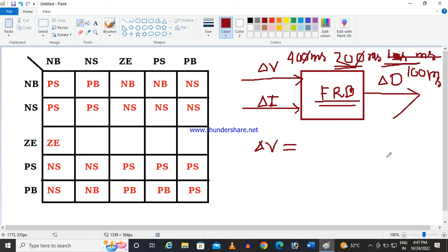So this is the basic thing for controller selection. If we decrease the switching frequency, it will increase the harmonics, or the power quality will be low. And if I increase the switching frequency, then its time period is less, so in that case all the conversion and everything should be done in a faster way.